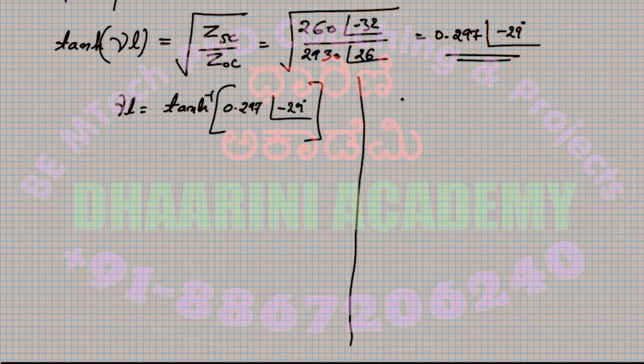We have the tan h of gamma L equal to, on the right hand side, some number, which is 0.297 at an angle minus 29. Anyway, we'll convert that into the alpha plus j beta format. But first let me go for the equation for tan h of gamma L. It's sin h by cos h.